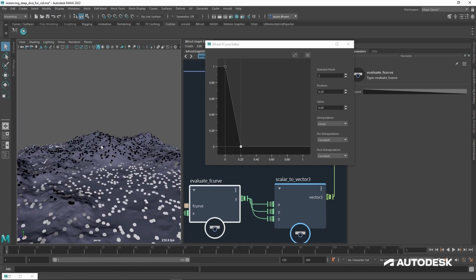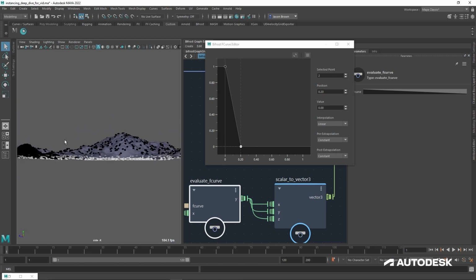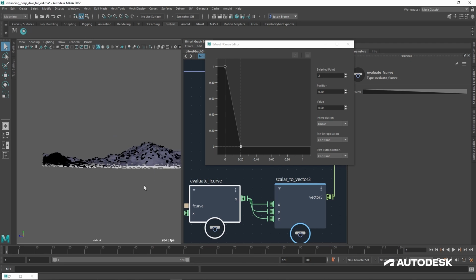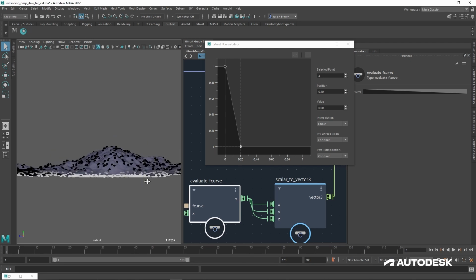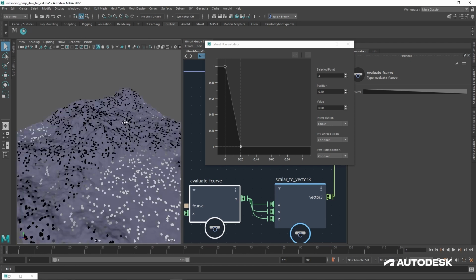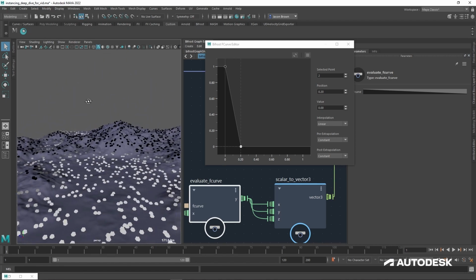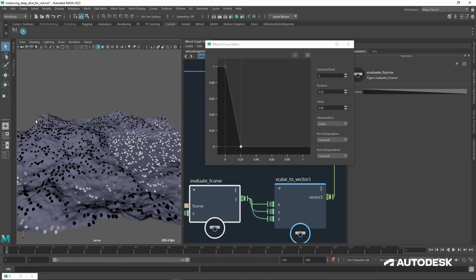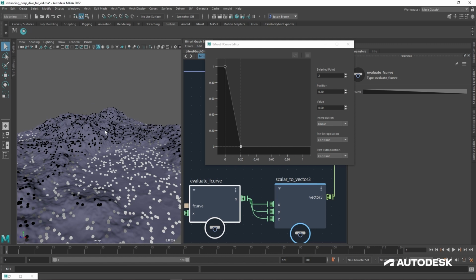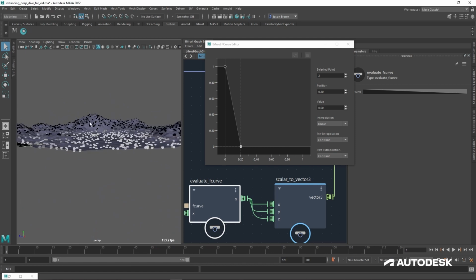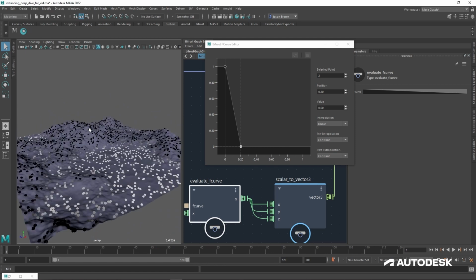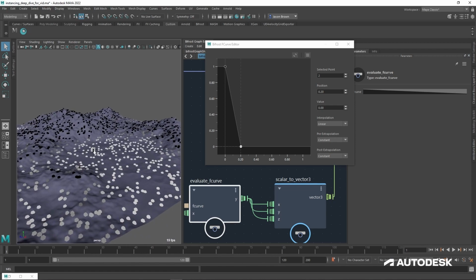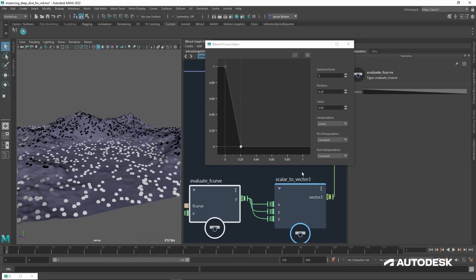So if you were to do the measurements and take a look at this side on, and we need to find this value and find out what a fifth of that value is, then you could probably map where everything started changing. But I prefer to put colours on the points so I can have a visual look at what I'm doing. So as you can see, what this is doing is highlighting all of our low-lying areas in white. And that's precisely what I want, because what I want to do is just scatter on anything that is low, is flatter, is not mountainous, anything that's lower down on this plane. So this is pretty much giving me exactly what I want right out of the box.